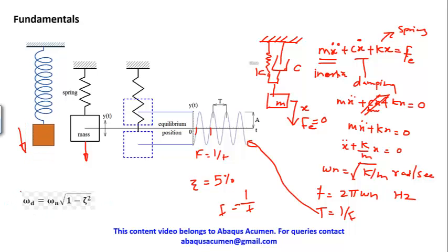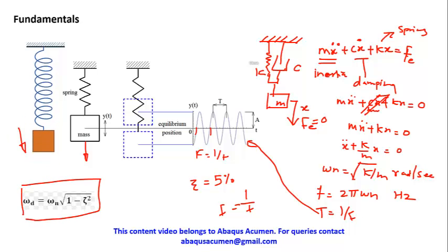Now a lot of the time this question comes up: why are we not doing a damped natural frequency? This is your answer. Your damping ratio is 5%. If you solve this problem, the ratio of undamped to damped natural frequency is the square root of 1 minus 0.05 squared, which is 1 minus 0.0025, and taking that root it is 99.95%. So putting in a damping and solving the Laplace equation, the frequencies between damped and undamped are not very much different.